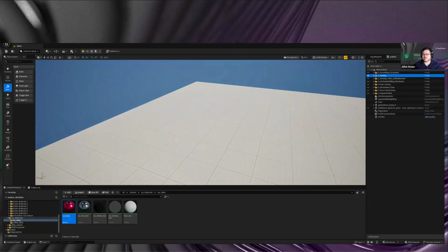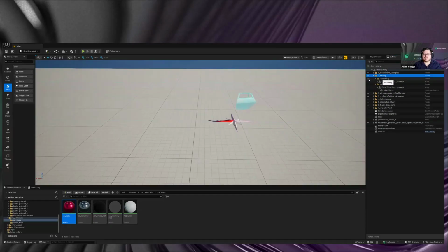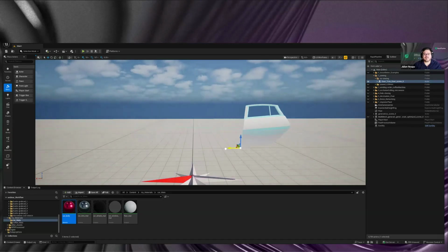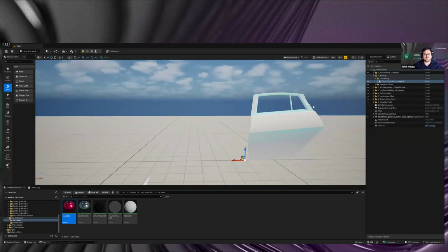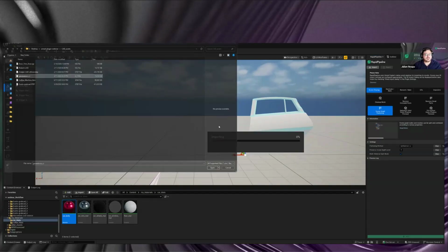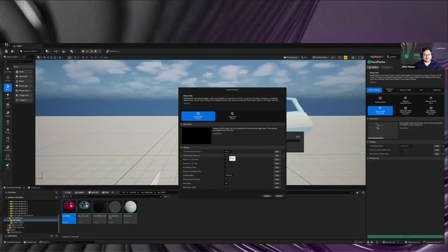Then there's one import option. Let me see if I can demo this a little bit here with the sewing. So when we do a CAD import, just bringing up the menu again, we have an option for sewing distance and sewing tolerance, and that's always set to 0.05 millimeter at the moment.